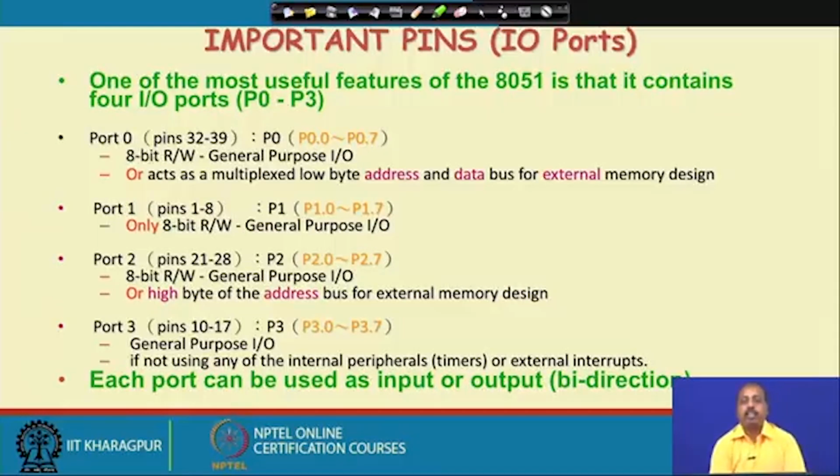On the other hand, in case of say 8085, we have to write in port and then the data is 8 bits only. Whether you use those remaining bits or not is up to the program, but the 8085 processor will read the 8 bit pattern, or when it is outputting it will output an 8 bit pattern. So, this port 0 is 8 bit read write operation.